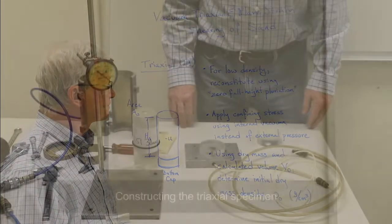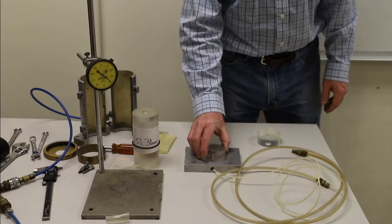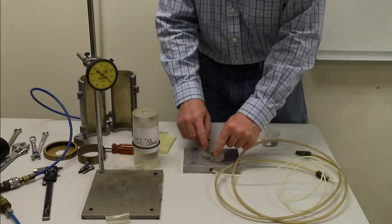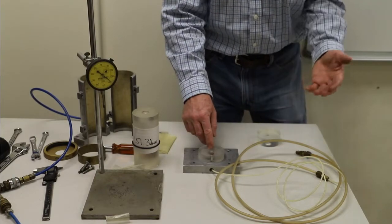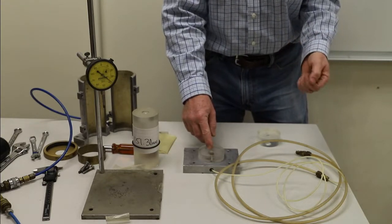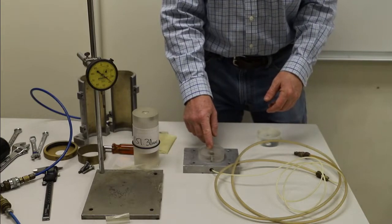And in fact, we're going to make an assumption during the data processing as if there wasn't any volume change going on. For constructing the triaxial vacuum test, we're going to build the specimen on a base cap that has a drainage line built into it. You can see the small tube connecting to a larger tube that connects to this sintered bronze stone, which is set into the cap. That's how we're going to have access to the internal pressures. And in many triaxial tests, that would be the pore pressure. This is going to be a dry specimen, and we're actually going to be applying the confinement, again, with vacuum that we apply through this drain line.